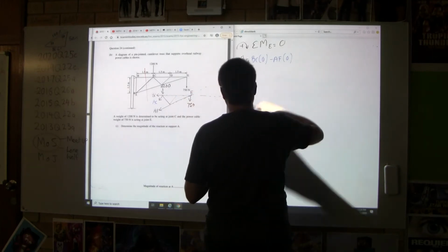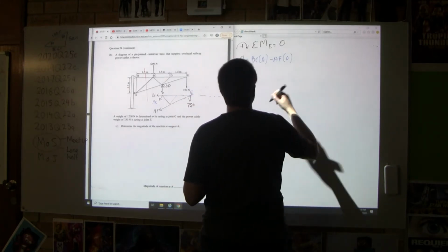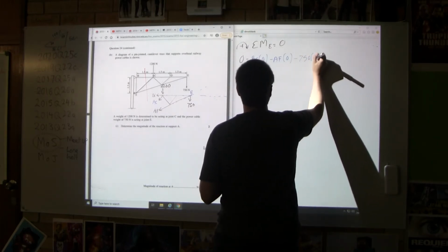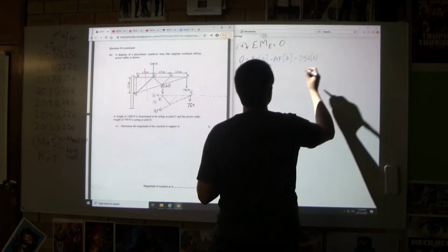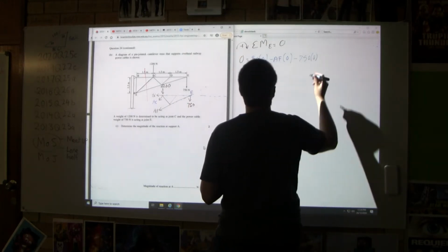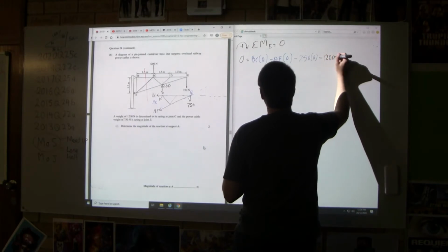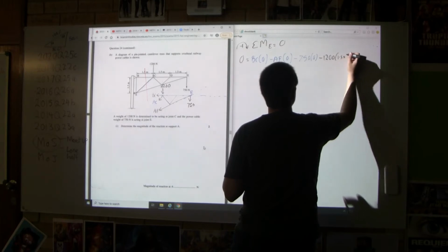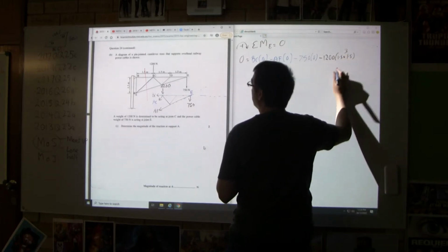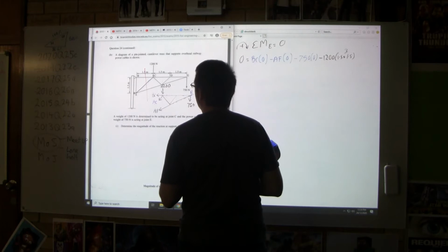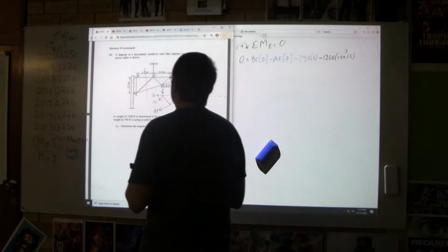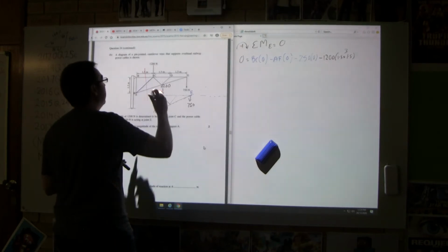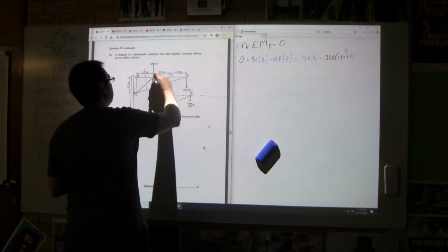then I'm going to say, using my black pen, 750 times 0, because that's touching, it doesn't have any moment. And then I've got minus 1200, and it is 3 meters away. I might write it as 1.5 plus 1.5 and then just write 3 above. And then I have finally this one. Oh, okay, well I've got to find my perpendicular distance. Okay, I guess I did get a bit excited. I thought this would be easier than it was.